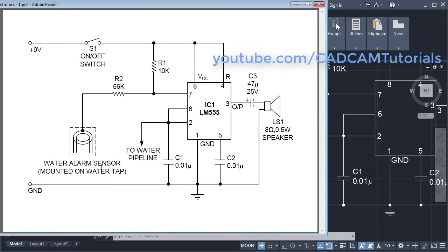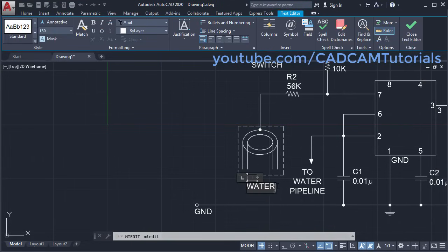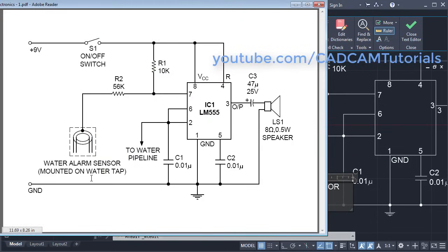Then water alarm sensor, double click, then to increase the size, take your cursor on this inclined line, press first mouse button and drag it. Then below it, press enter, mounted on water tap.